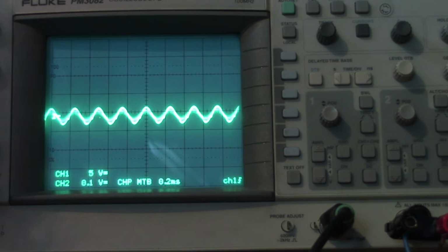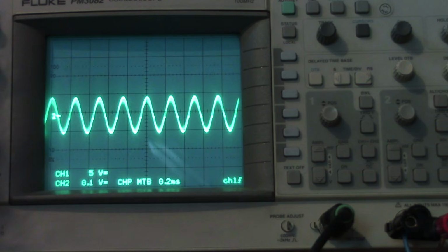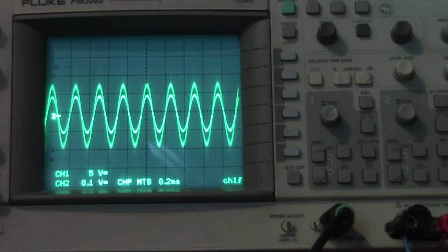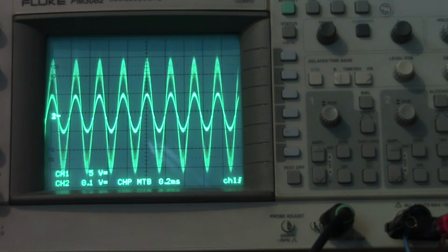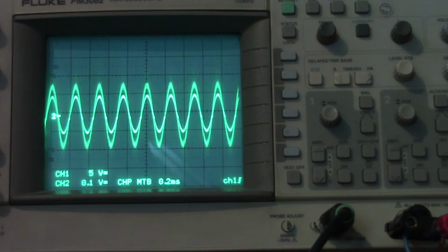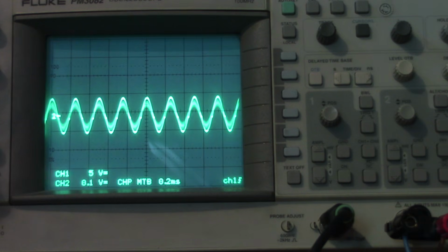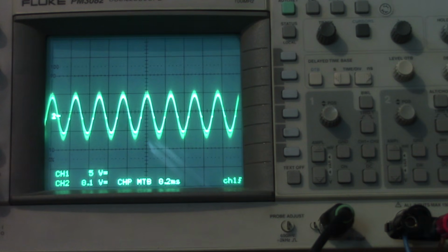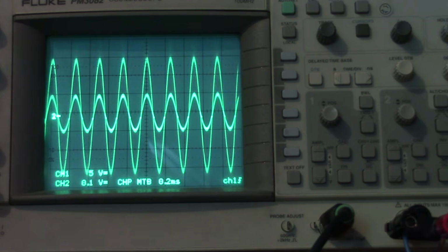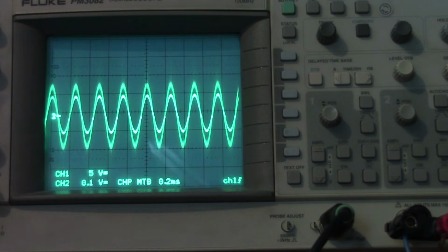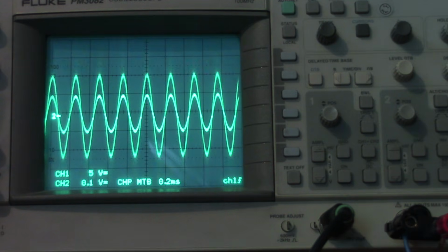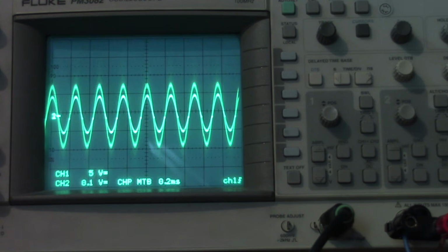But watch what happens when I get above a certain amplitude, which I think is around here. If I keep increasing the volume on my phone, the output signal does not change much, and it stays roughly the same. And so this is our circuit doing its thing, right? So once we get to a certain threshold, which again is around here I think, the output signal is limited to about the same amplitude. And so our automatic gain control is keeping the output signal at a certain level.